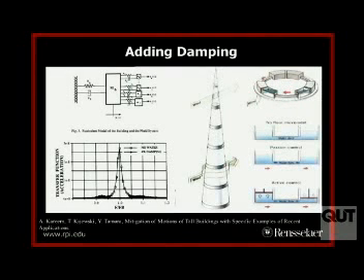Now, of course, another way of handling this problem is to increase the damping of the structure, and that's a fairly classical approach used by structural engineers and wind engineers. So there's a whole range of different technologies for using dampers in structures, just like we now have much better drives in our Ford Fiestas or Ford, whatever the Focus or whatever the Ford is here, instead of a Model T because of dampers. You'll get a much better ride in a tall building with a damper because, again, you're doing the same sort of thing. You'll have a reduction in the response because you're really increasing the energy dissipation in the structure by the use of dampers.